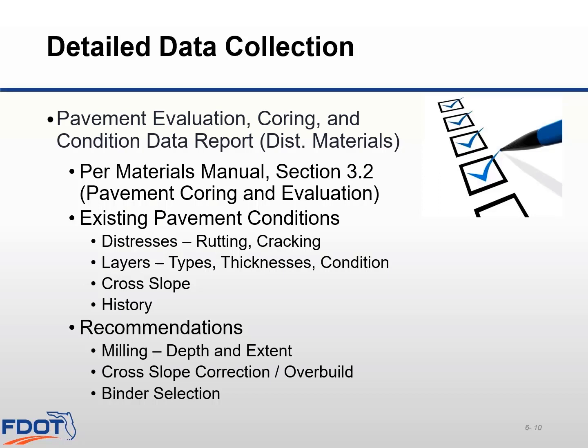The pavement evaluation information should be used by the designer to carefully evaluate the possible causes of the current distress, so that the distresses are not simply repaired, but are also prevented from rapidly reoccurring. The designer should not be satisfied with simply providing an adequate structural number, but should also consider other factors. An example would be an unstable lower layer that has repeatedly contributed to rutting in the past. By studying the pavement history, this problem could be identified and evaluated and a deeper milling depth set. A concrete overlay or reconstruction to concrete are other alternatives to consider.